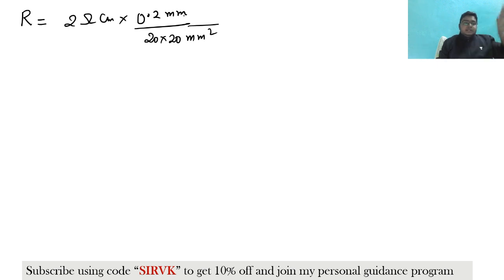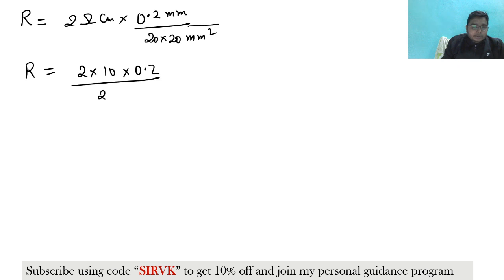So by this, see here, rho is in centimeter and this is in mm. Fine, just convert it into centimeter. Just multiply by 10 and convert it. After the conversion, you will be getting 2 into 0.2 by 20 cross 20. Fine. Now you are getting the resistance value as 1 by 100 ohm, which is nothing but 0.01.